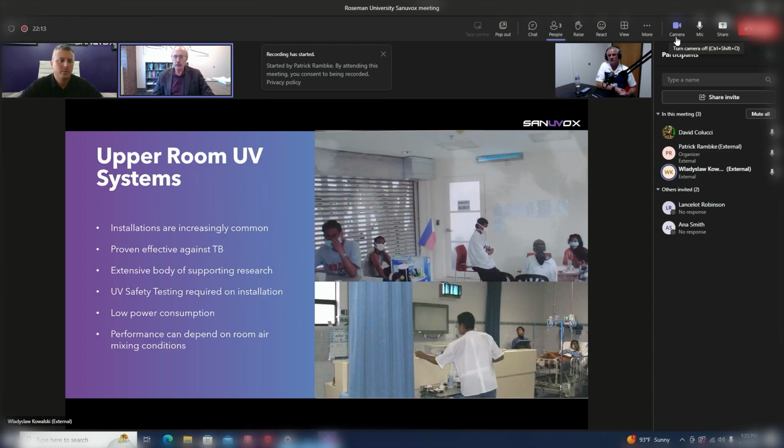Now we have upper room UV systems, which have been tried and tested for many decades. They're very effective against any airborne pathogen. There's an extensive amount of research demonstrating their performance. They're low power consumption and easy to install. However, the performance can be highly dependent on room air mixing conditions. It's something we don't know a lot about.